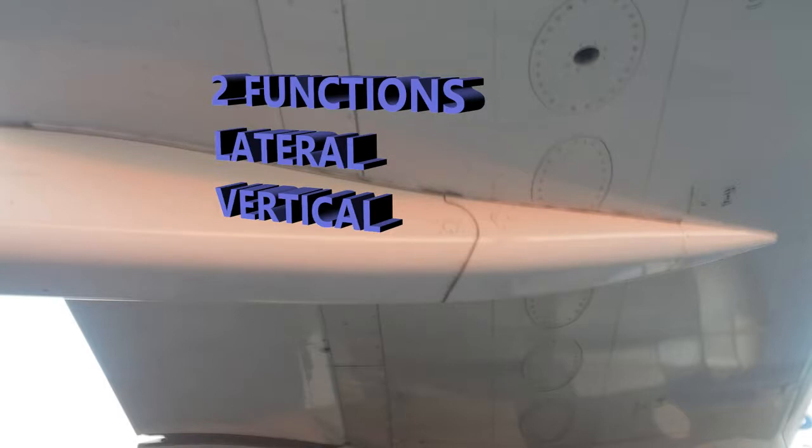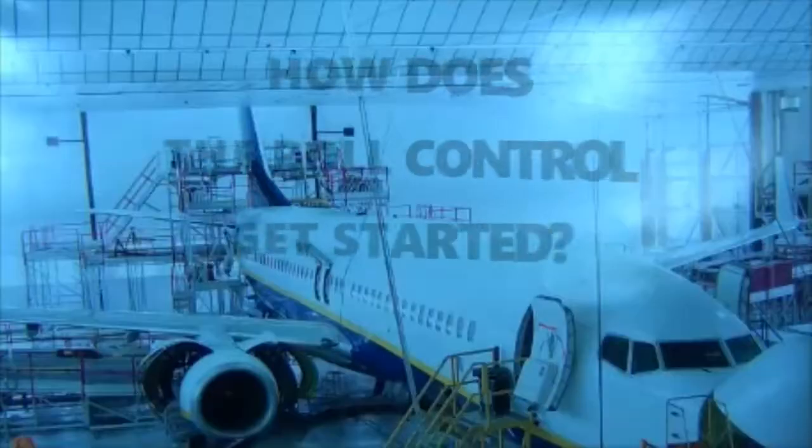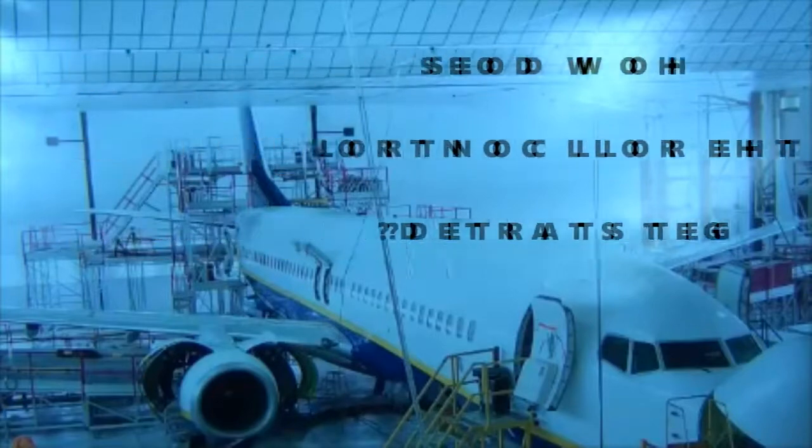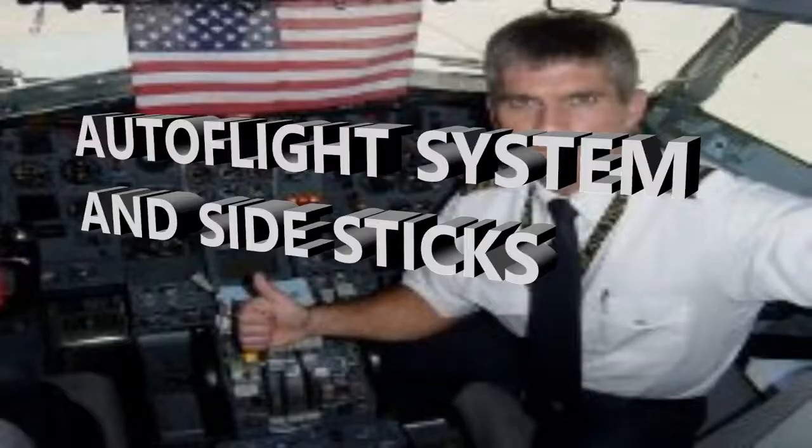The roll command, how does it even get started? How does the plane even begin to roll? It has to be given a command to do so. And that's going to be started obviously with the auto-flight system or the side stick units from pilot input. That's when it starts, and all that information, like I said, is sent to the computers, both your primary and your secondary computers.